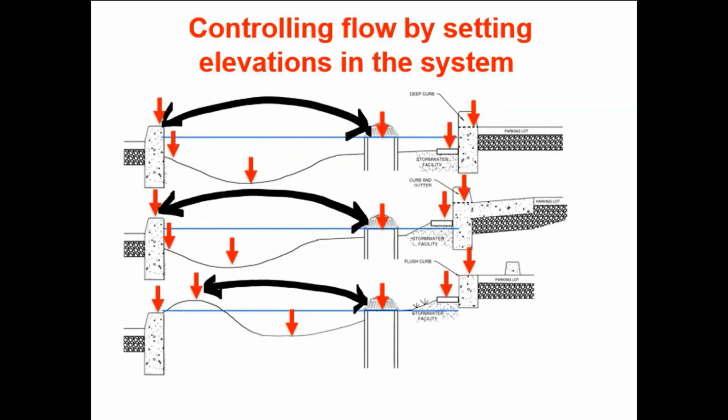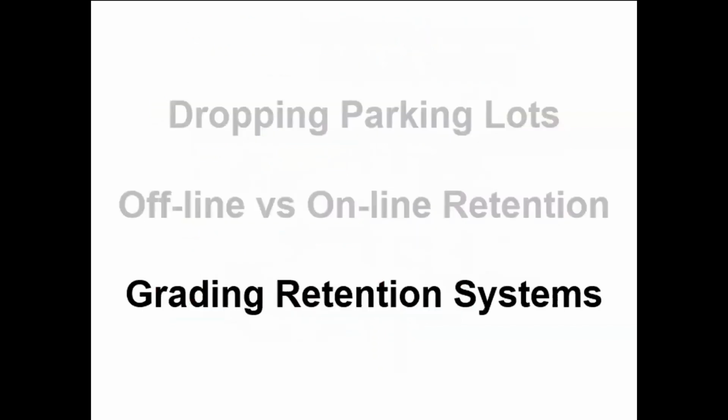The raised drop inlet needs to be below the curb cut in all cases, and the bottom, the low point, needs to be defined so that we know how much water is going into and being held by your bioretention system. I'd advise you go back and look at the slides that give those specifics again, and then we'll go into more detail in the next lecture.